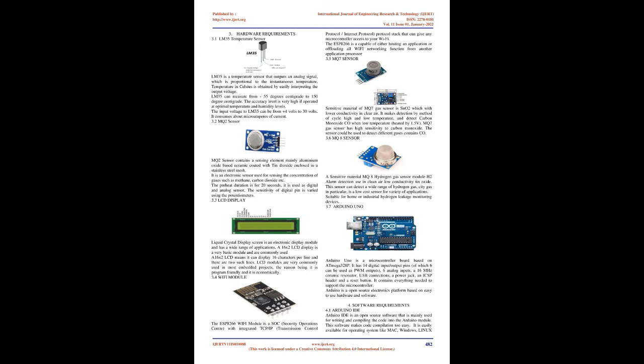2. Proposed system. A typical condition monitoring system for a transformer is capable of monitoring various components like oil temperature, gas in oil, moisture in oil, oil level, voltage, current, etc. The main objective of this paper is to design and implement an embedded mobile and IoT-based system to measure oil temperature and dissolved gases like carbon monoxide, hydrogen, and methane using sensors.